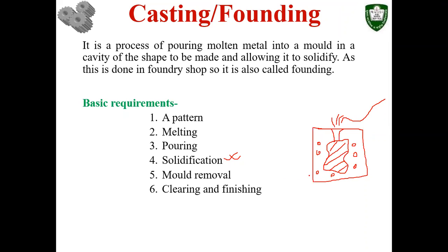For die casting, there are ejector pins. And for sand casting, you just break the mold and take out the final part. And in some other cases, you can use the vibratory shaker. Using the vibration, you can break the outside mold, but the internal part will be intact. So there are many other methods you can use for the mold removal.